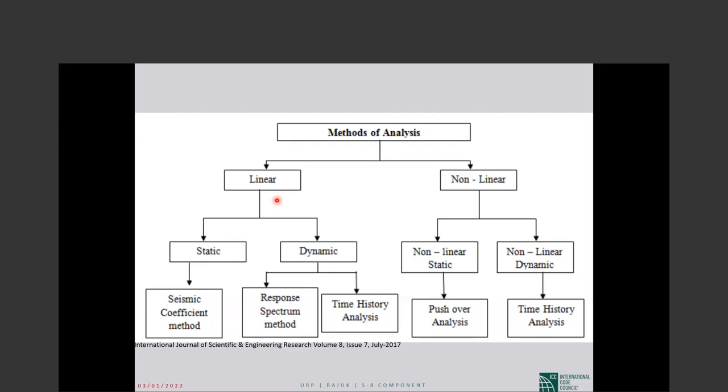Therefore, it's easy for the force control actions. For every one of the actions that are categorized as a force control action, we just need to know the strength capacity, the force bearing capacity of that, and compare it with the demand. But how do we calculate the capacity?